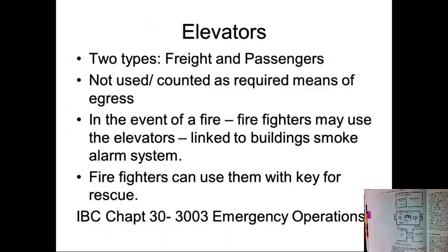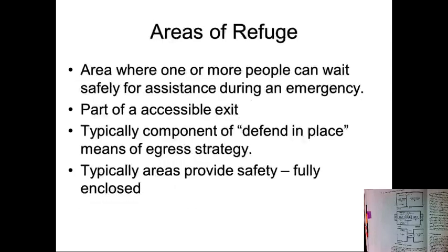So elevators, there are two types: freight and passenger. They are not counted as a required means of egress. In the event of a fire, firefighters may use the elevators linked to building smoke alarms, etc. Firefighters can use them with a key for rescue. If you look at IBC Chapter 30, that talks about emergency operations, which we'll get into later on.